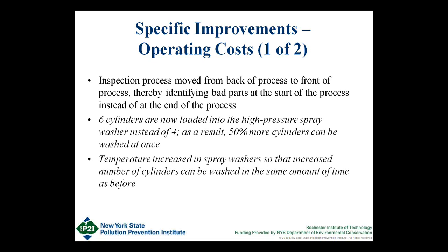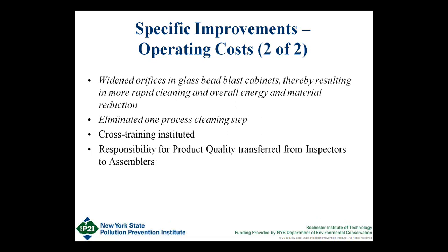We were able to increase the temperature in the spray washers so that they could wash more cylinders in the same amount of time. And then this one here, this widening of the orifices in the glass bead blast cabinets, this was not something they were comfortable doing at all on their own. They really needed us to be able to pilot this kind of on our own in one of our laboratories and be able to prove that this really would work and make the process more efficient. So we also were able to completely eliminate one of their cleaning steps.